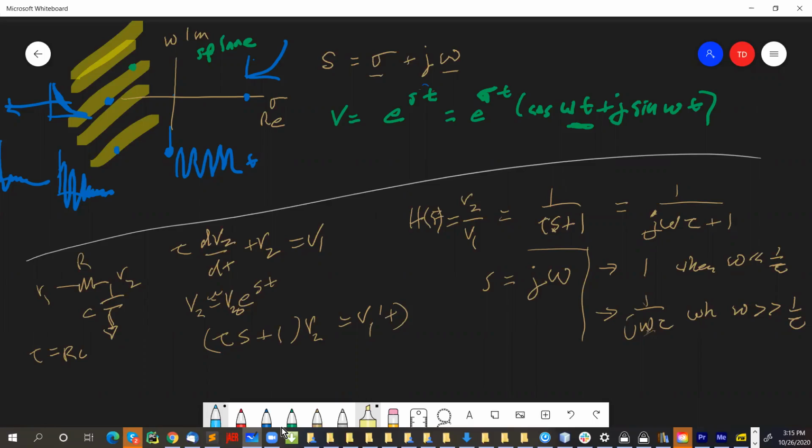Okay, thanks. But remember, you can still get oscillation even if the s is negative because of some large signal saturation. Like for example, suppose the feedback in your circuit saturates. That means there's not enough feedback. So then your circuit can still oscillate even if the s in small signal is negative. I don't remember what the name of it is, but it's a very common problem with circuits that you don't take account of the nonlinearities, the saturating nonlinearities, and your circuit ends up oscillating even when in principle it shouldn't in small signal.